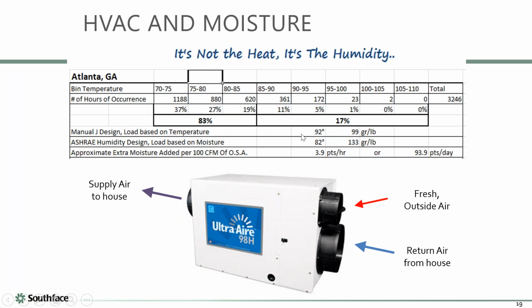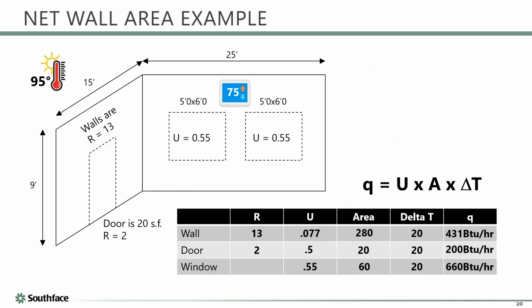But the reality is our peak moisture day is a third more moisture. That is a lot of grains, and it's on a day when it's not that hot. So again, it gets into this need for, and I always try to build the case for, variable speed or inverter driven or equipment that can adjust itself automatically is really, really critical.